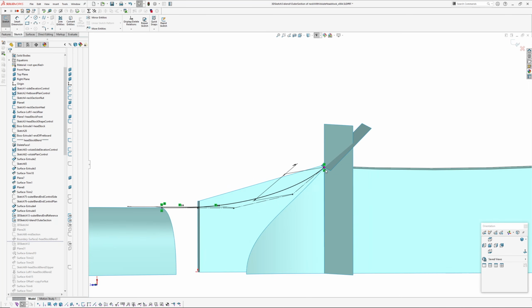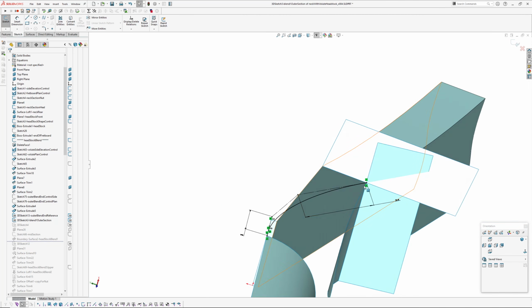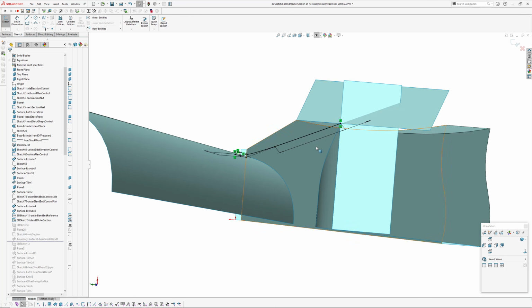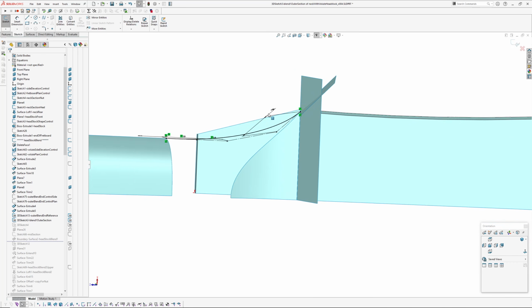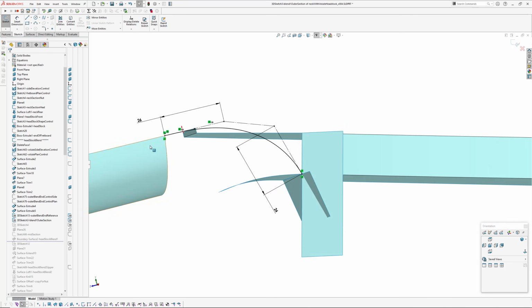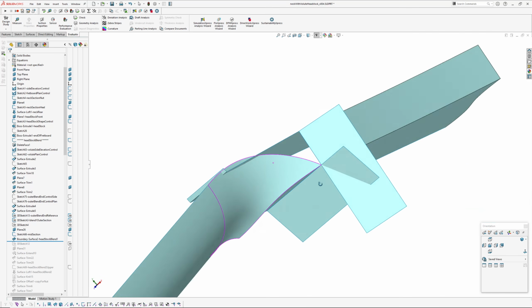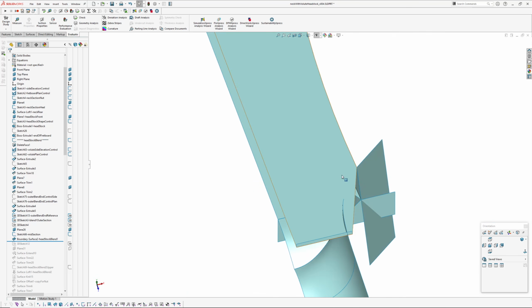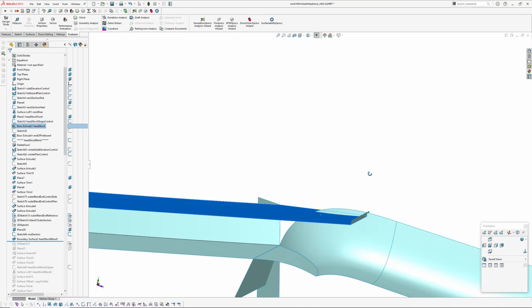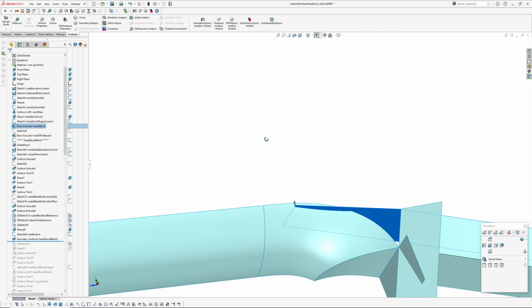So that means that at that end of the 3D sketch, I can change the angle in this plane. I can also change the angle in this plane, and in the 3D sketch I can control the spacing of the control polygon segments, because the front edge of this volute, where it intersects with the top of the front of the headstock, is actually resultant.